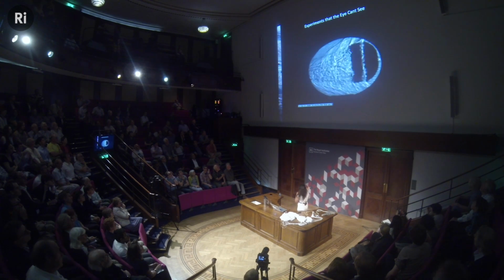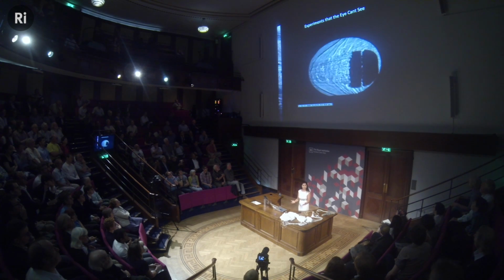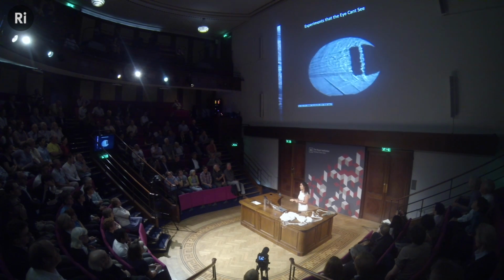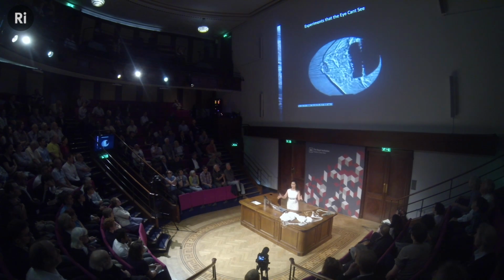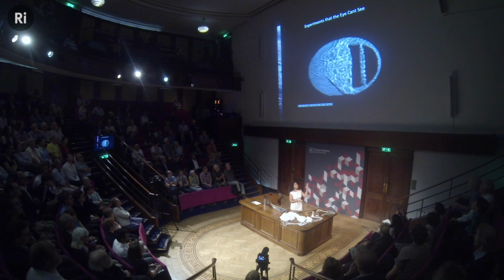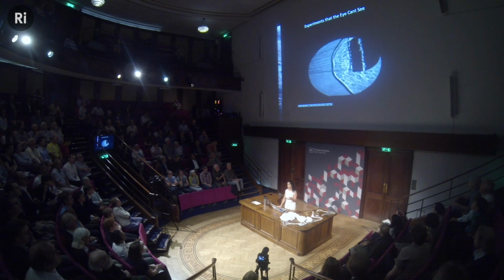And so we validated the physics of what was happening, we validated our simulations, and then we were able to design our parachute to be strong enough, perform well enough, so we could send it to Mars. And so even though we did full-scale tests to do structural testing, we also did little subscale tests to verify how it would actually perform in that difficult, dangerous supersonic environment. And we were successful, and of course we did land on Mars, so it did work.